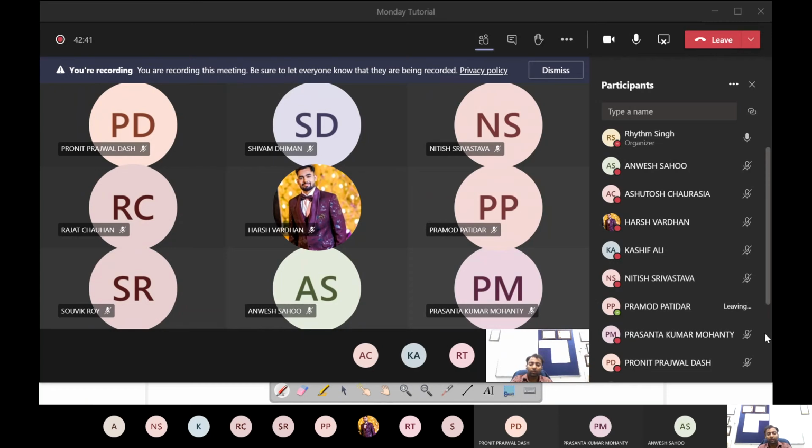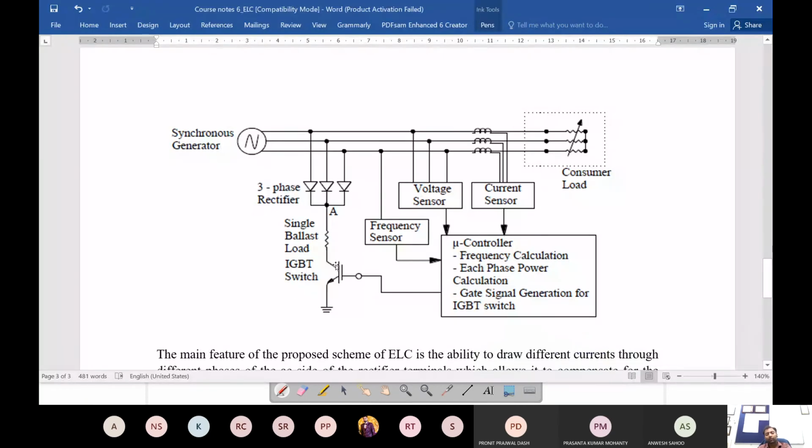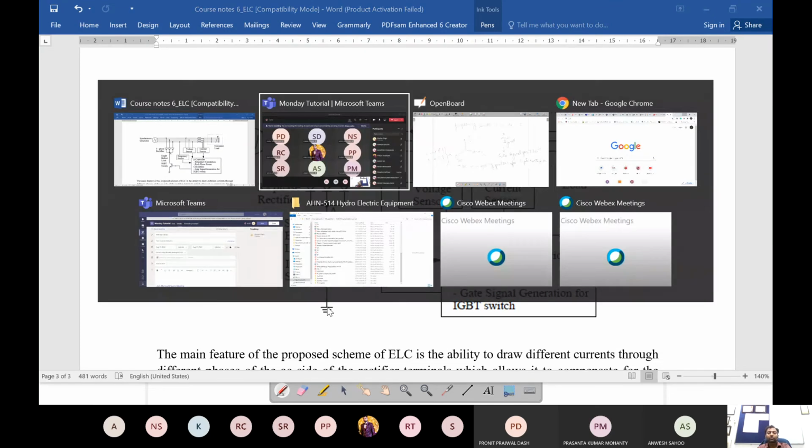So it's like this is a switch here. You can think of it as a switch. When you don't provide a signal here, then the switch is open. The circuit is open. The switch is off. So there is no conducting path available here. But when you give a gate signal, then this switch goes from off to on mode. And when the switch is on, the circuit is complete, the path is complete, right? So the current will flow through this. For conceptual understanding, this is how we need to understand the switch.